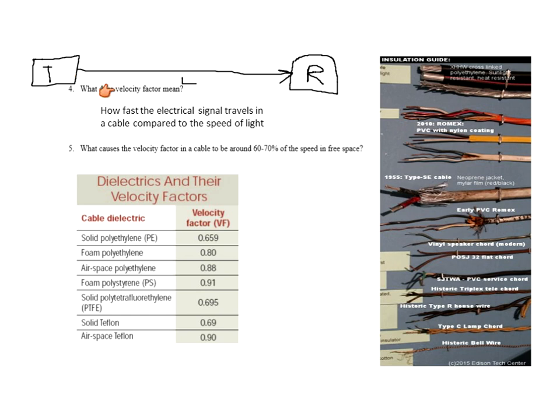How fast it gets there is called the velocity factor. The velocity factor in a line is much slower. It's slower by about 30%, 30 to 40%, which means it runs at about 60 or 70% of the speed in free space. So what causes that? The type of insulation, or in this case, it's called the dielectric.